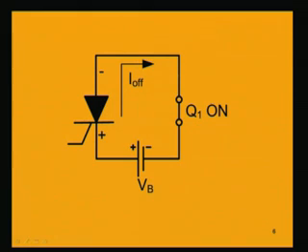So, conduction is taking place in the transistor, that is why current is flowing and making this thyristor off by making the polarities of the anode and cathode like this, just opposite or reverse biased. So, this is the forced commutation which also makes the thyristor turn off.